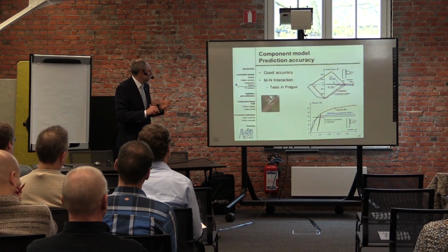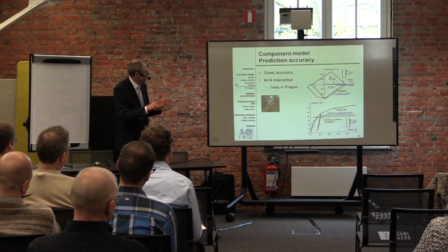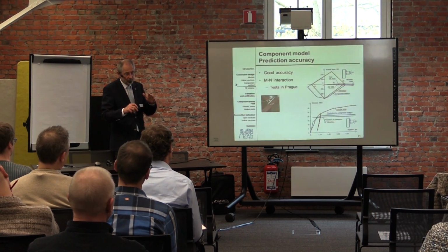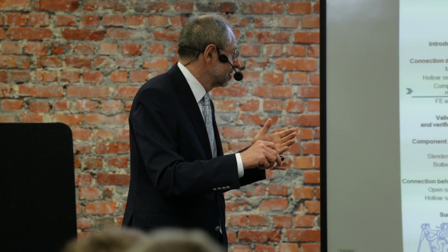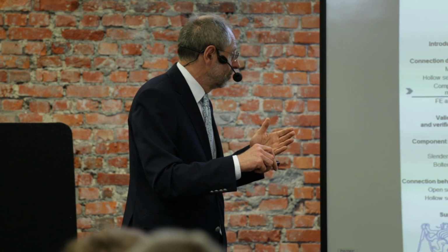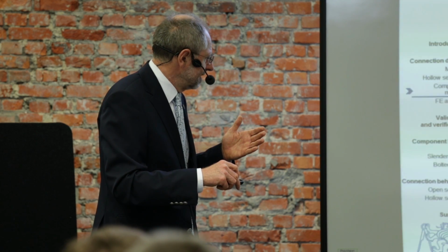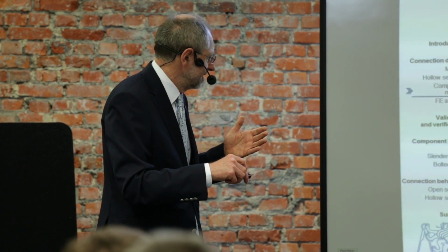This is a bit complex: a beam to column end plate connection with 6 bolts in 3 bolt rows, loaded by MN interaction, normal force and moment. We are using linear interaction, or we may calculate by the component method. Here I have a result of the test, and you see how accurate even the prediction of stiffness is.